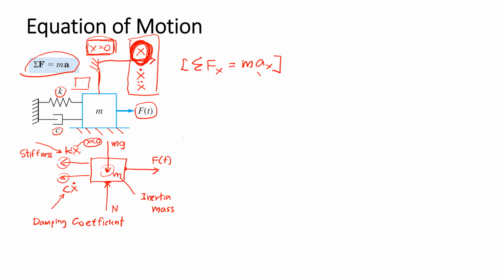If x is less than 0 and it is multiplied by the spring constant K, the force generated by the spring, we assume the direction to the left-hand side, but the magnitude will be negative. In the physical phenomena, it means the direction of the arrow is wrong. I mean, the direction of the real force should be opposite to the arrow. If the value here is less than 0 but we point it to the left-hand side, it means in the real meaning the force should be on the right-hand side, which makes sense, right?